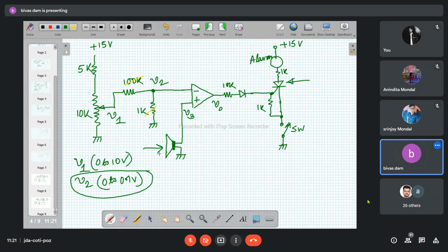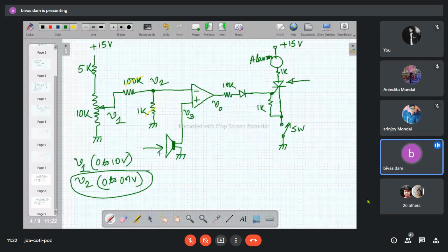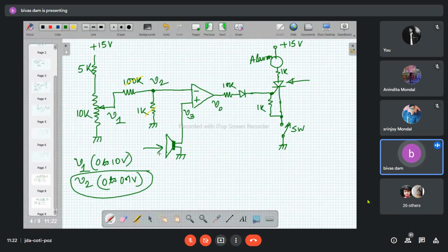So in that position, the input difference voltage has become negative, just negative from the positive. And at the output, how will that be reflected? Minus V set. The output has switched to the minus V set at that particular wiper position. So we are monitoring the output signal at the very wiper position where the output is switching its state from plus V set to minus V set, and we will freeze the position there itself.